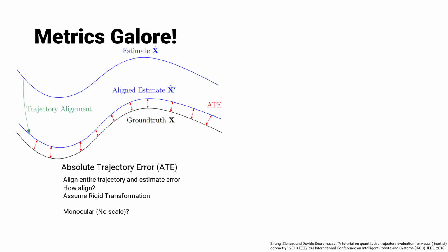So how do you do the transformation? In this particular case, you do what is called a similarity transformation, which means that scale is also a free variable. The problem with this absolute trajectory error is that it's sensitive to the time when the error occurs, which means that if the alignment is not exact to that particular time, it will drift apart. So it's not that great.